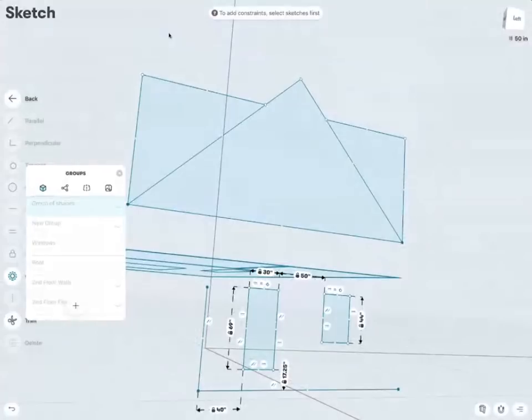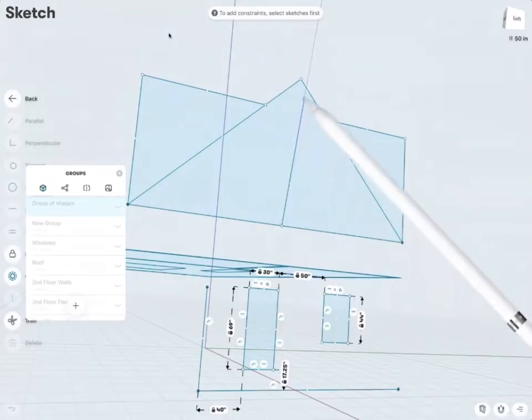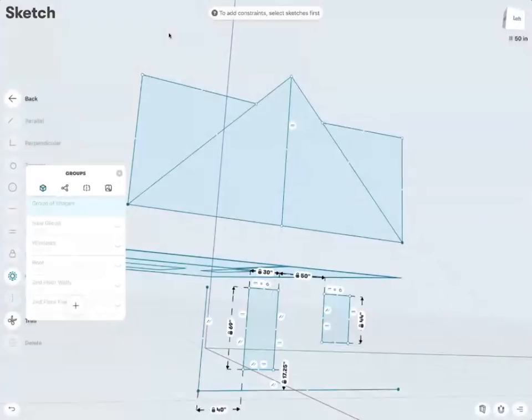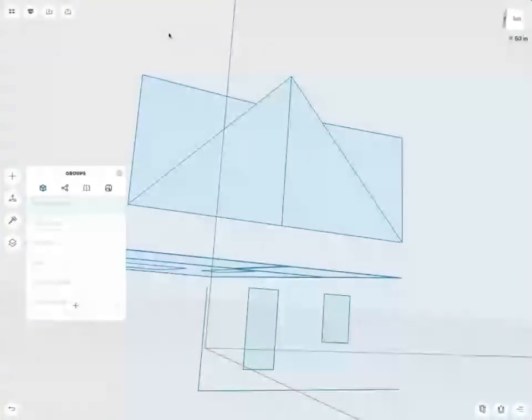The nice thing about the sketch engine in Shaper is when we work with basic geometric shapes, like a line, it has a midpoint and the roof is 90 degree. So essentially this point has to be 90 degree or perpendicular above this midpoint. So I could connect this midpoint to the tip. Then I say, hey, this one should be vertical. And then I could say this should be 90 degrees. Perfect. So this is also establishing the height. I cannot move this point up or down anymore. So that's the way I created the roof line.